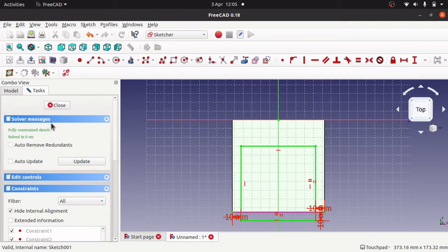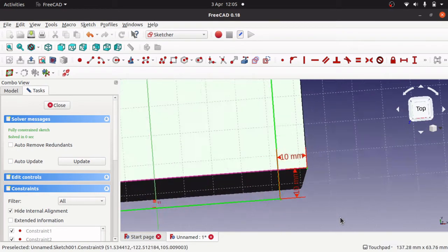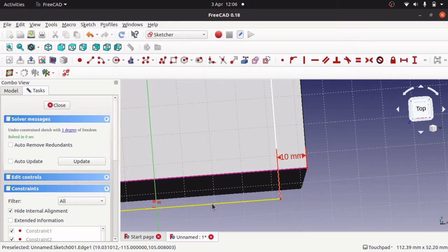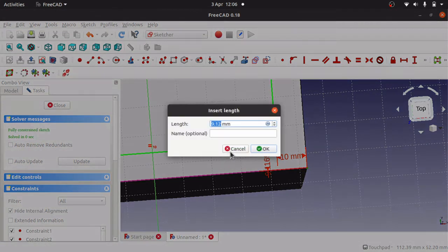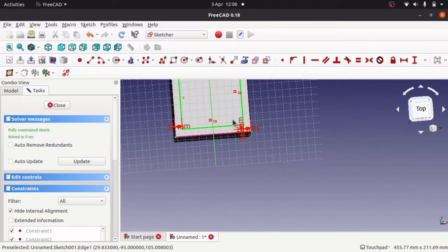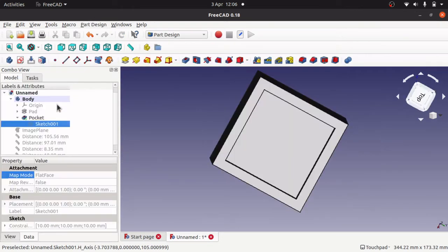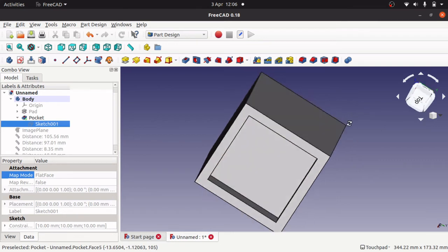So what we'll do is go back into our sketch, and what's probably happened is that's moved, and you can actually see that's moved. And if we zoom in, you can see it's taken 10 millimeters from that base there, so we'll just delete that one. We'll just move this up and place another one in there at 10 millimeters. Okay, that. See, that's locked down now. We'll just zoom out, click on top. Let's move that back into position, just close that, and then that is actually connected to the top.